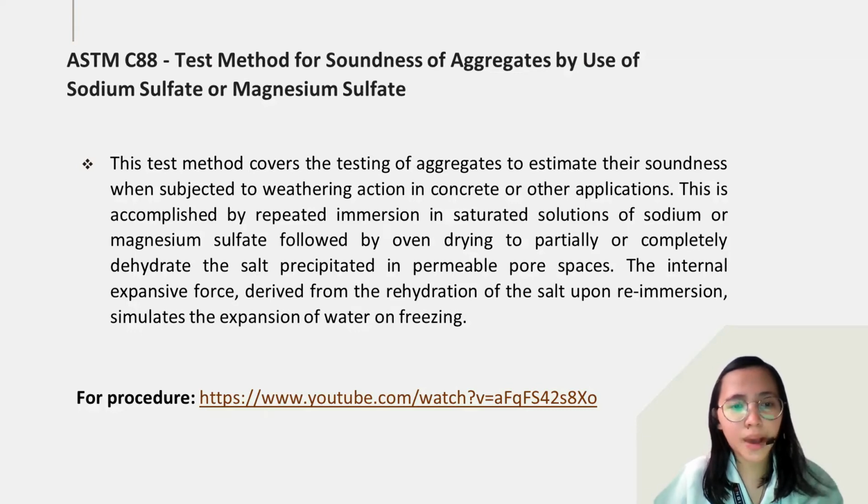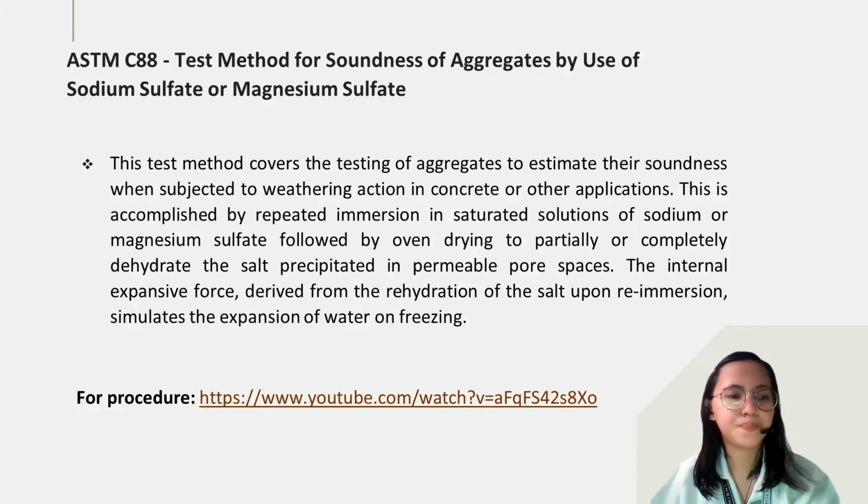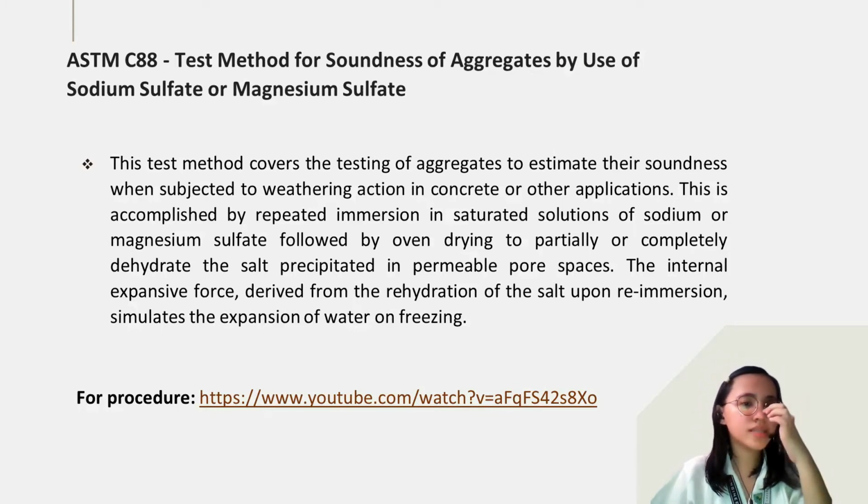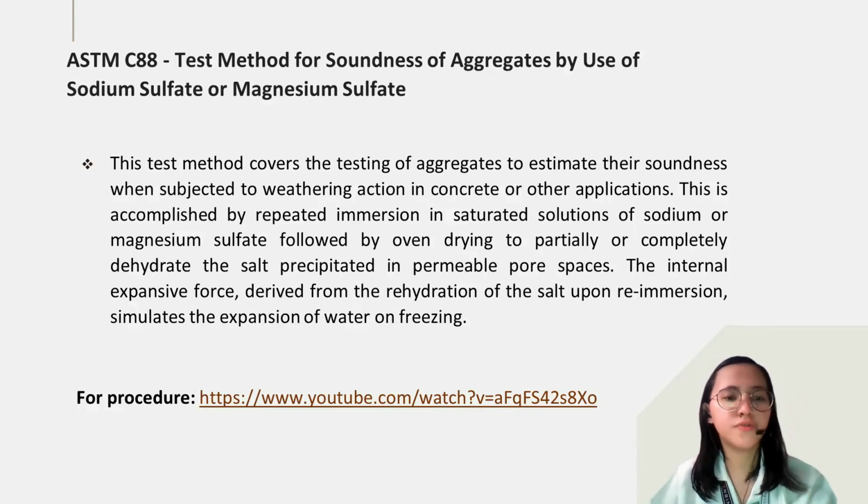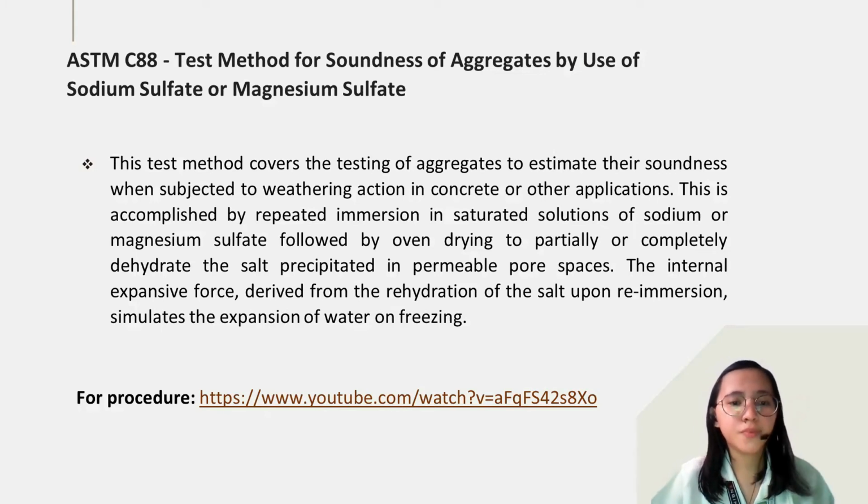The internal expansive force derived from the rehydration of the salt upon re-immersion simulates the expansion of water on freezing. So this method provides a procedure for making a preliminary estimate of the soundness of aggregates for use in concrete and other purposes.